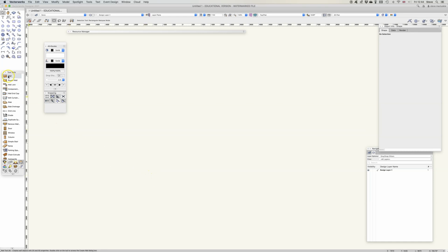So when you have surveyed your space and you have your measurements, it may be tempting to go for the wall tool, and it's absolutely fine to go for the wall tool. That is one way of doing it. When you select the wall tool, you have these options here: left control line mode, center control line mode, and right control line mode. These are the only three that we're really interested in. Don't worry about this last one. And actually the center control line mode is less useful and almost never used in what we do.